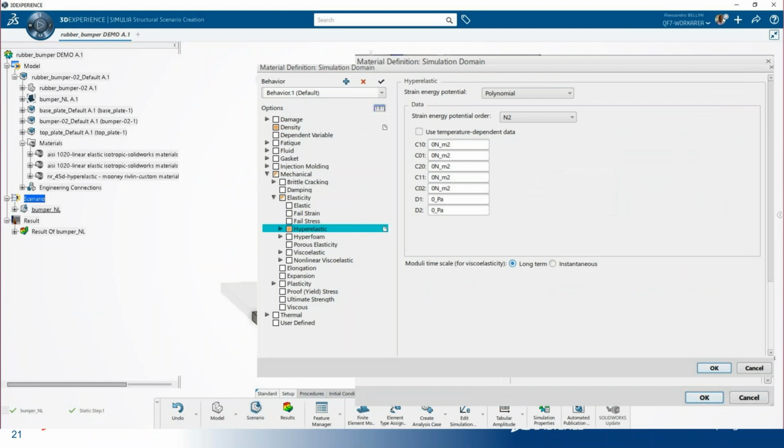So the polynomial model here, Mooney-Rivlin at the power of 2, is C10, C01, C20, C11, C02, plus 2 compressible constants. Here again, the compressible constants D1 and D2 are optional. The first one is, as before, linear, and D2 is on the power of the second order. So the question is how to work out which are the constants for your model given the curves.